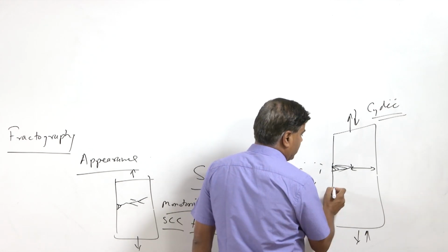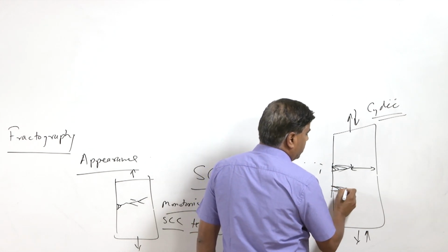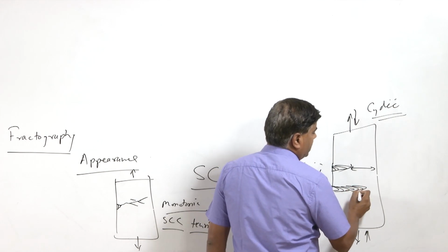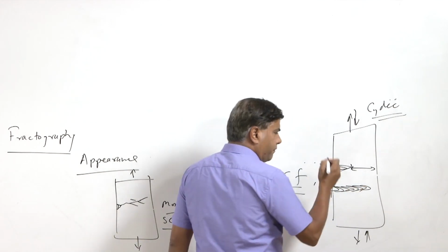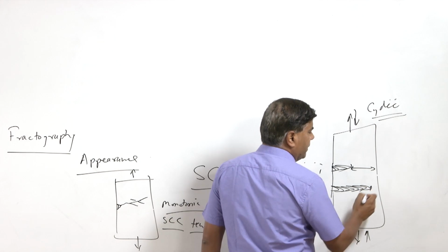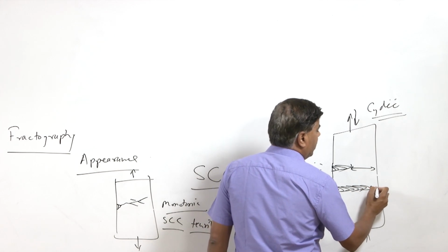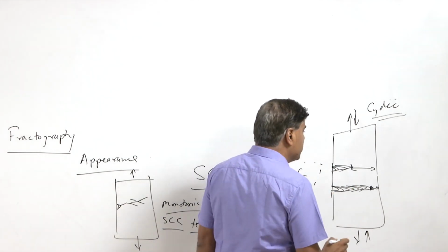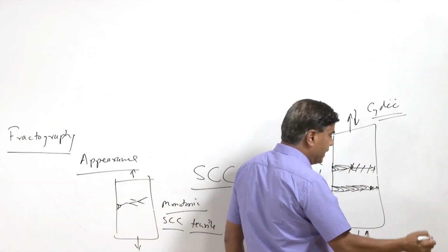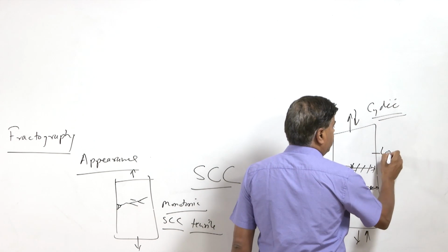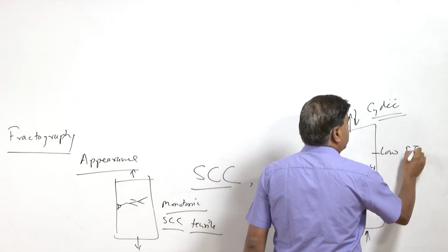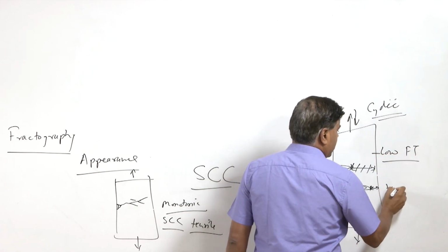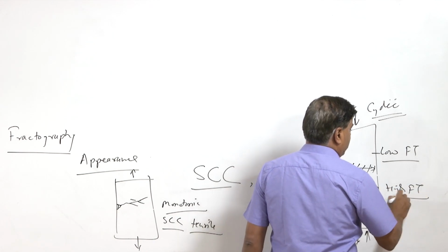But in a high fracture toughness material, the crack can grow gradually, and thereafter the sudden fracture will occur when the left-over load resisting cross sectional area is reduced to a great extent. So, in this case the load resisting cross sectional area is large in the case of low fracture tough materials, and this is the case of high fracture tough materials.